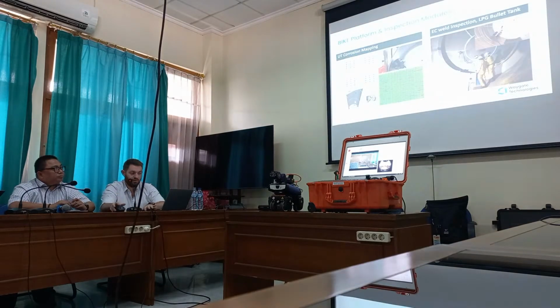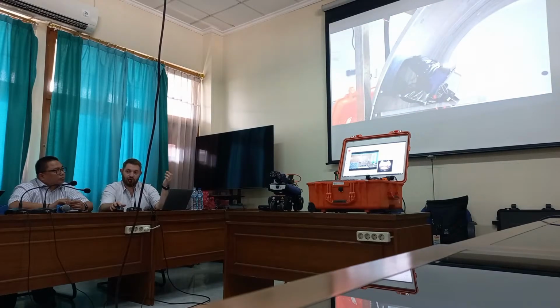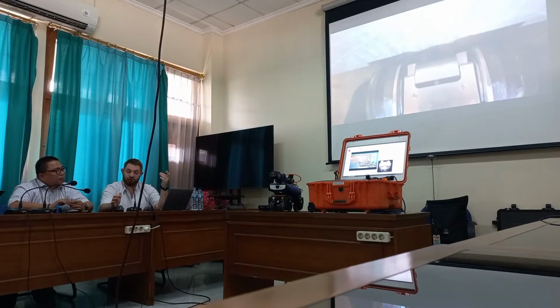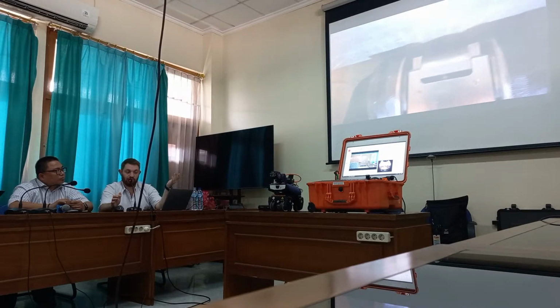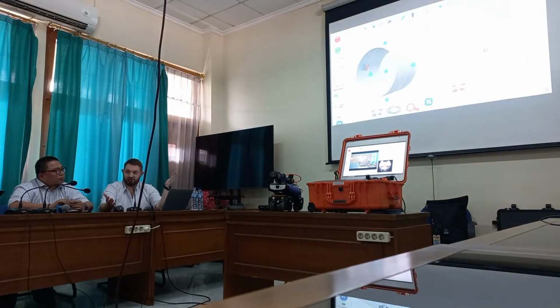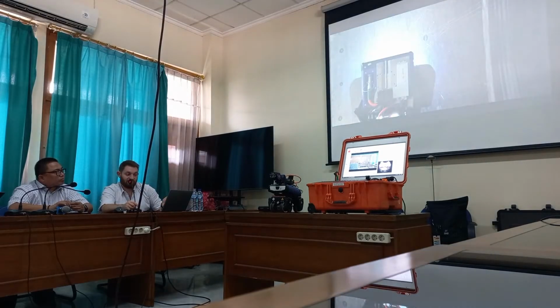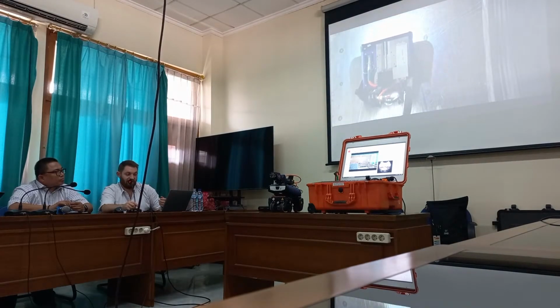Because the hardware is designed to move and operate through different types of environments, we can rewrite software quite quickly to give it structured measurements or structured movements. So in this instance here, we're doing some very basic forms of corrosion mapping with the roller probe, or more effectively, it's just continuous line scans in a B-scan format. So this is our 3D model of our test mock up in Switzerland. And we can see here that the robot self-drives itself backwards and forwards.